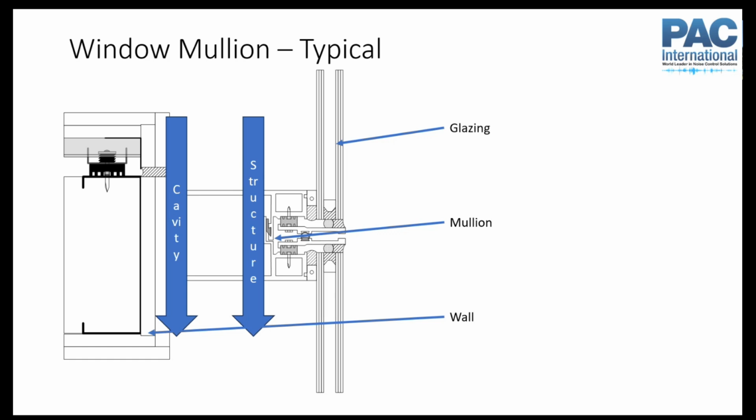But even if you just were to seal that gap, that helps, but you still also have the structural path through the window mullion. I mean, this is 2 layers of drywall on either side of this wall, right? That's 4.5 pounds per square foot on either side of this, right? You have a lot less mass than that in a typical aluminum window mullion. So you've got this weak structural path too.